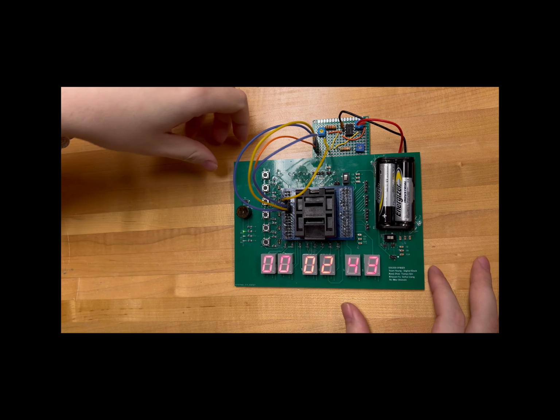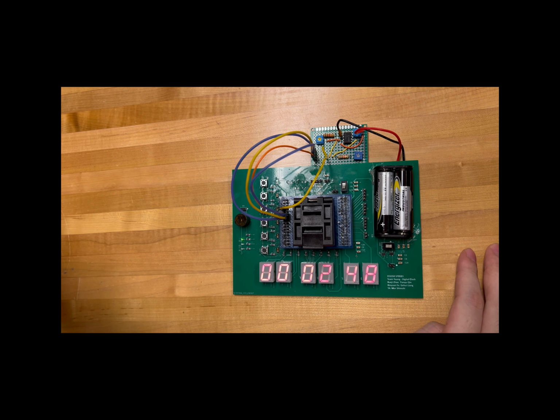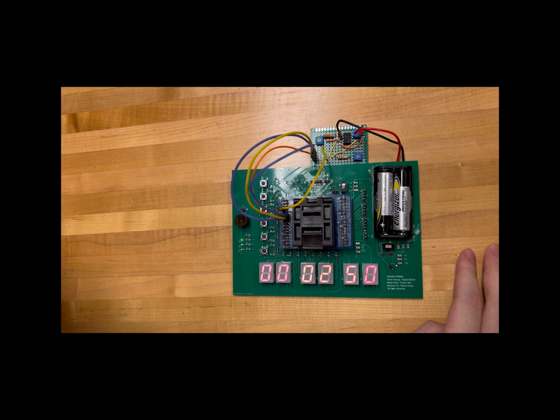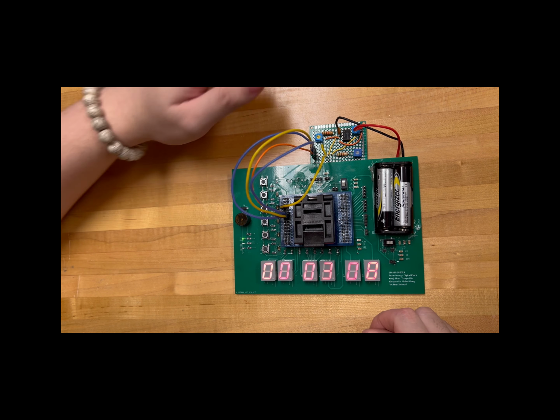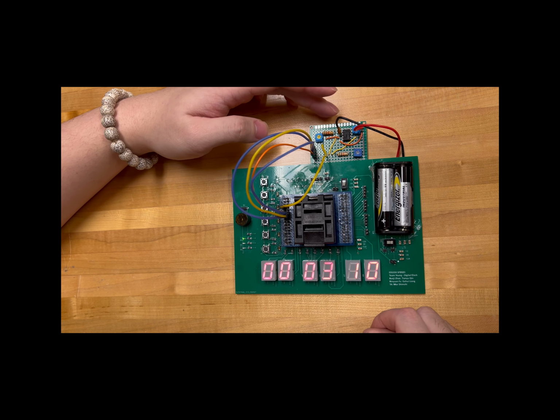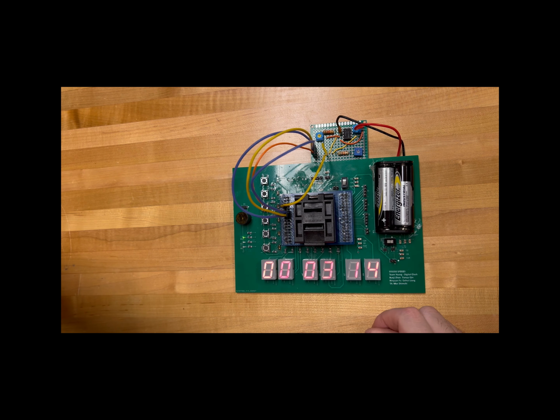Okay, so here is our design of the digital clock. We use 2 batteries to provide 3-volt voltage to power the whole system. On this side we have 6 buttons as input, and for output we have 7-segment LEDs, a single LED, and a buzzer. We used to have the crystal circuit on the PCB board, but unfortunately it doesn't work. So we use the 555 timer to generate a 32 kilohertz clock for our chip.